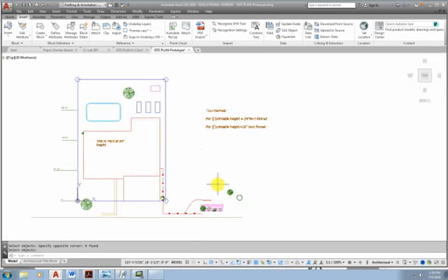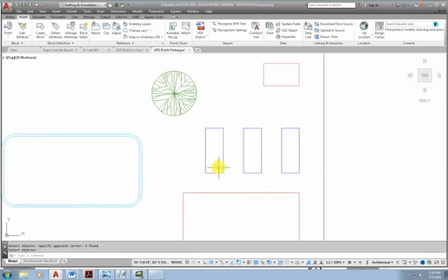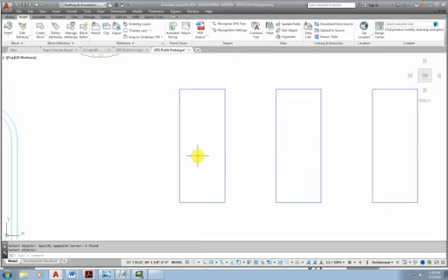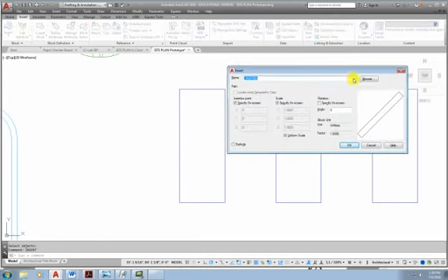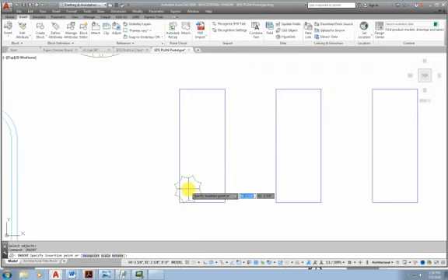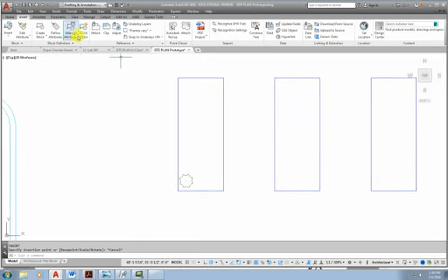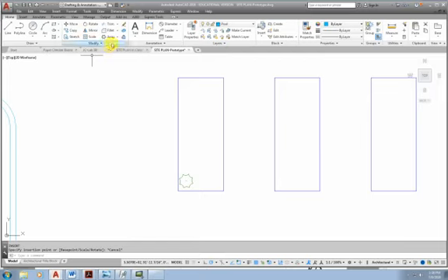And then when I come up here, I'm going to put in my bushes. And so what I can do is say Insert, and I'll say Bush 1. And I'm going to use a uniform scale factor, and so I'm going to say OK. I'm going to put it right about here, and then I'm going to put it at 0.5 scale, and I'll OK that. And then what I'm going to do here is to array it, and so I'm going to use a rectangular array. Now certainly you could copy it and go through that, but if we use a rectangular array, it'll be very precise.